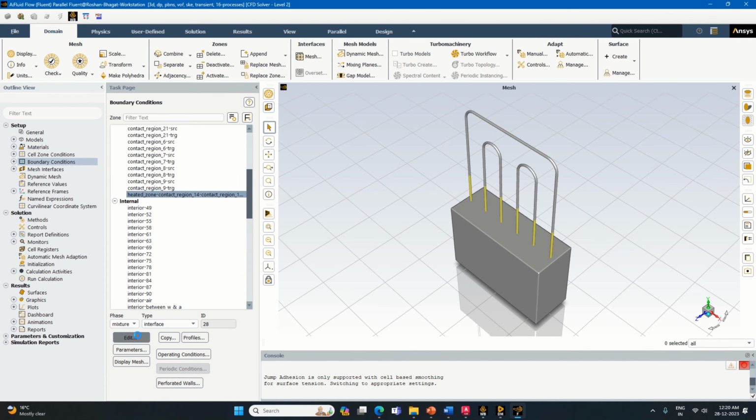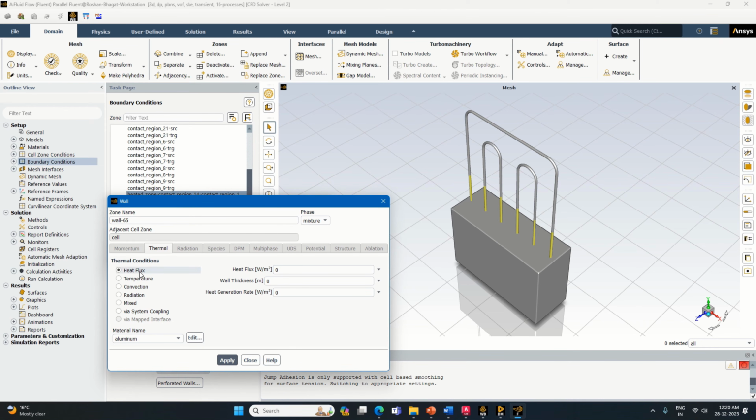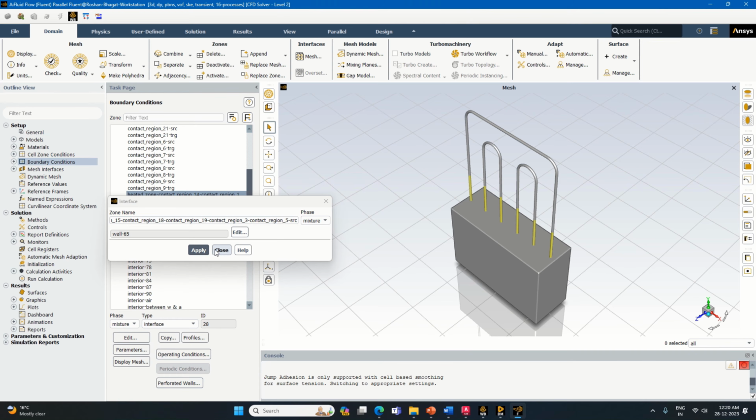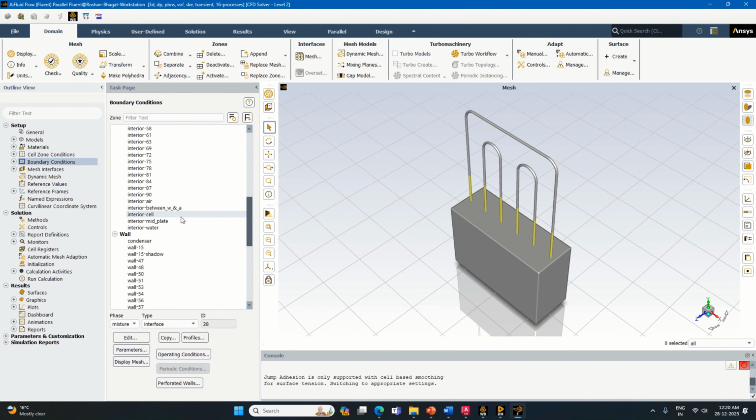The heated zone also again I put it here, with boundary condition as temperature, let's say 323, make it nickel, make it close. So boundary conditions are applied only at one place.